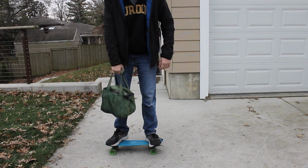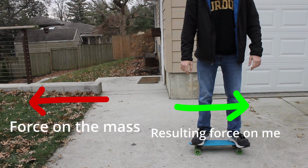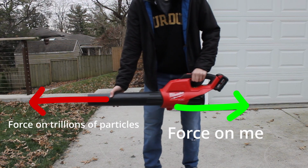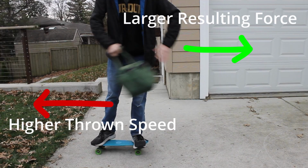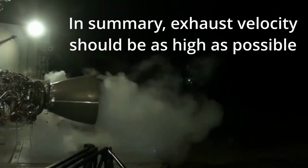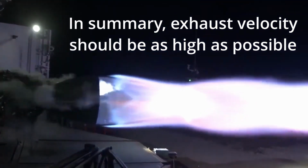A good example of this is a guy on a skateboard with a heavy object. Throwing the object in one direction will push him in the other direction. A rocket motor works on the same principle, only with trillions of little particles instead of one large weight. Additionally, if our hypothetical skateboard man were to throw the mass at a higher speed, then a larger force would be generated and he would be propelled in the opposite direction at a proportionally higher speed. Just rolls right off the tongue. The same is true for rocket motors. We want to accelerate our exhaust gas to as high of a speed as possible in order to generate the maximum amount of thrust per mass unit.